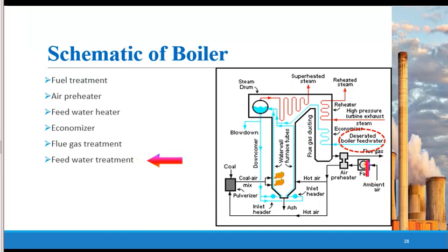Otherwise, it will damage the boiler, because the water may contain oxides and other impurities which, if they enter the boiler, will precipitate on the surface, or may cause corrosion of the surface of the tubes, of the heaters, or of the boiler.